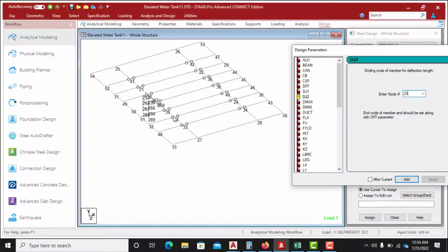That's the correct thing. It's not correct to check deflection from here to here because there's no support here. There's no support here. There's no support here. This is where we have support. This place and this place. So the deflection check is supposed to be between this and this. So you know how the beam is going to hug when it's loaded. That's the correct thing.